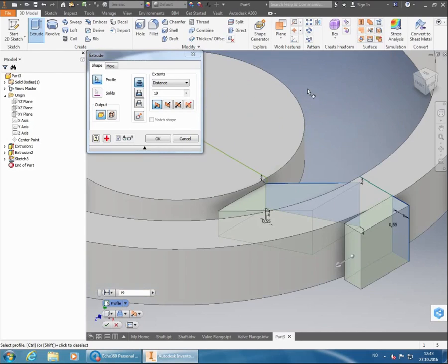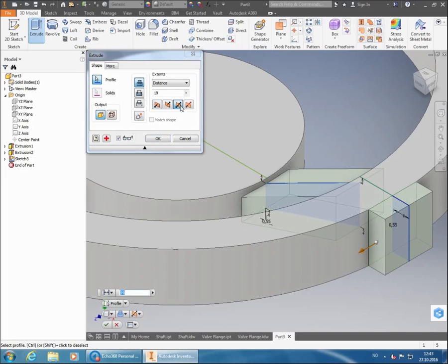So right now, we managed to select the correct outlines on the sketch, but right now it's trying to extrude everything in one direction. And that's no good. We need to extrude it symmetrically in 2 directions. So we need to go over to the window here and choose the symmetric option. So we've gotten the symmetric one in. It's doing it in both directions from our sketch.